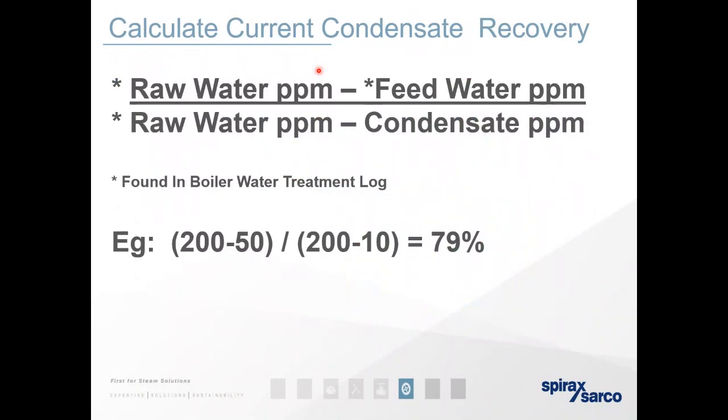Also, there's a similar or easier option, rather than a frame: you can also put an exhaust vapor condenser. I do believe that can also be used on top of the reservoir or the condensate recovery unit. FREM as a term in Spirax just means flash recovery equipment, so we cover a whole range of different products. It doesn't always have to look like the skid system that I show on these slides. It can be individual pieces of equipment.